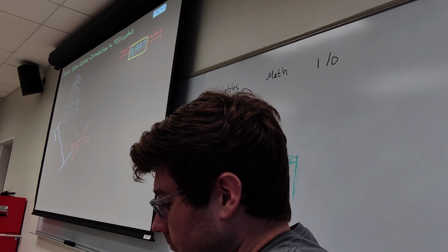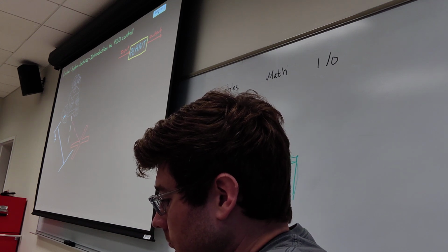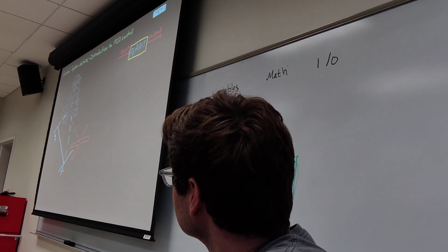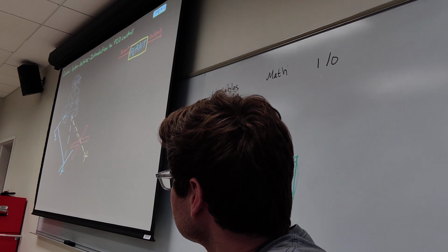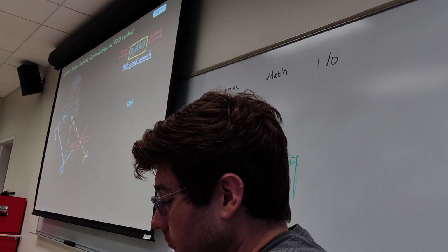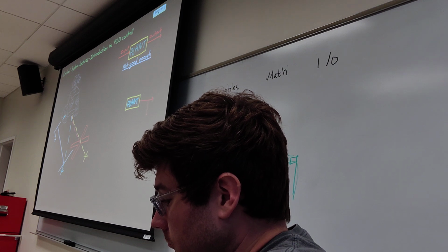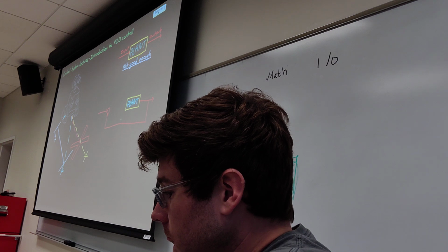And open loop commanding is perfectly fine for systems that don't change much or where accuracy isn't as important. However, what if there's some dirt in one of the wheels and the robot veers off to the side? Or if the robot's slightly faster than you had predicted? In both of these cases, the robot won't stop on the red X because it has no way of compensating for these errors and making adjustments on its own. Now the solution then is feedback control, which essentially means you're sensing the output of the plant and feeding it back so that the system can make adjustments accordingly.